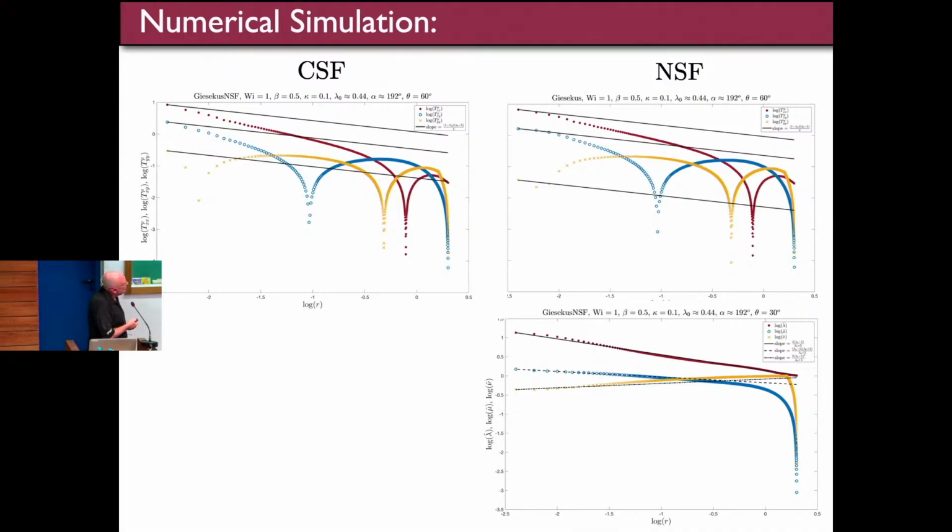Let's have a look at the natural stress. These are our natural stress components, lambda, mu, and nu, against the radial distance. Far faster convergence to the behaviors. And in fact, there's a link between the natural stress and the Cartesian, so we can turn these results into the Cartesian equivalent. And this is what the natural stress gives us for the Cartesian components. And we can see that we're now starting to get to that theoretical behavior. So the natural stress not only converges faster, it gives you better estimates of the Cartesian stresses, basically.